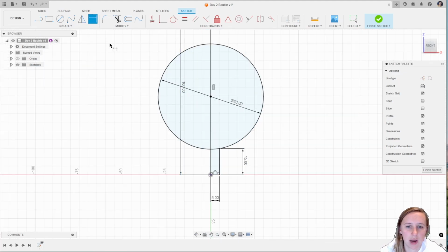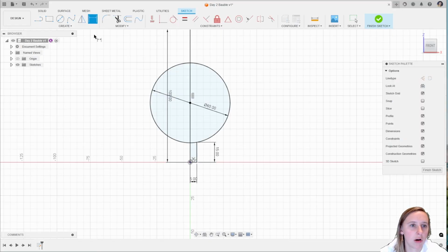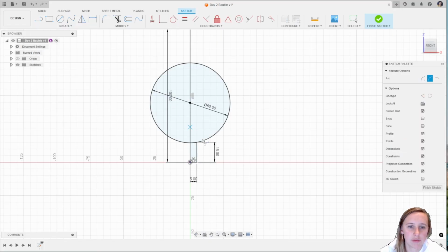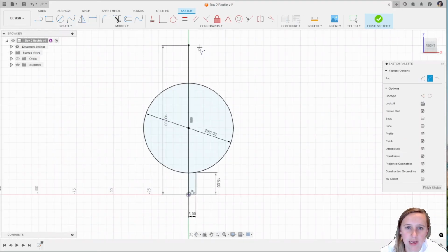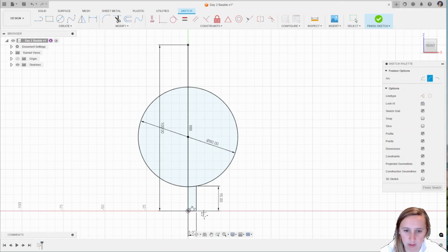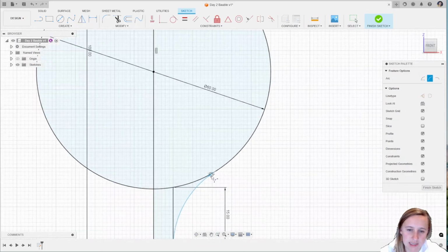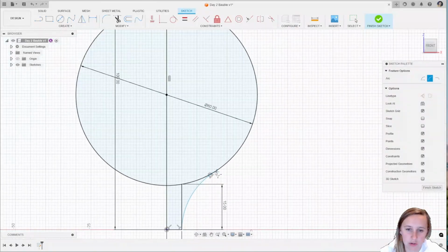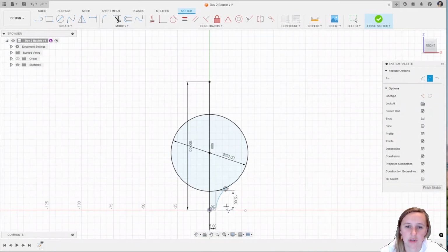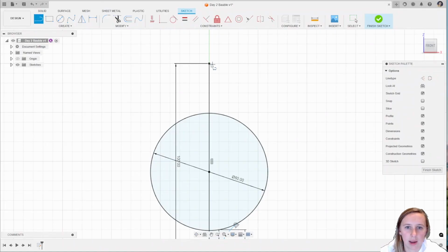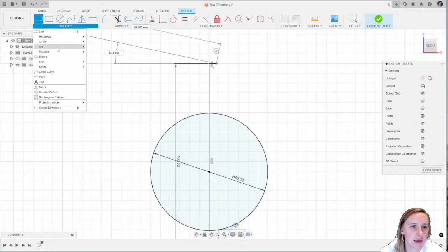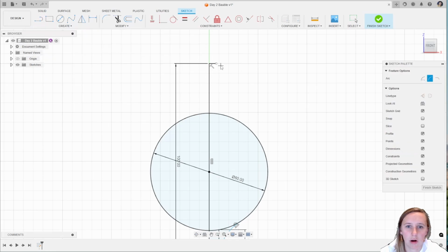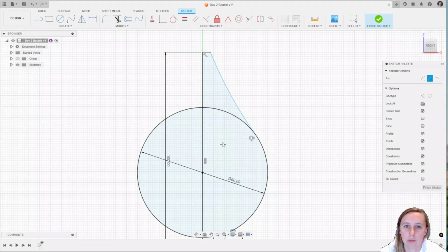And then I'm going to add in a couple of arcs. So create, then arc, 3-point arc. The first one is going to be down here. So adding that arc in there, and I want to add in this tangent constraint here. So just making sure that snaps to a tangent constraint. Adding one more line at the top, bringing that across, and then another arc, 3-point arc from that line to that line. And again, I would like that one to be tangent.